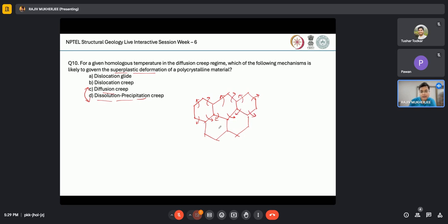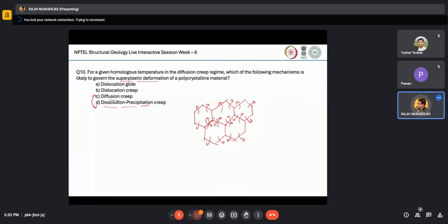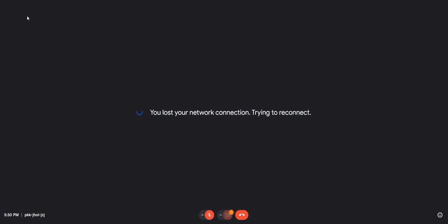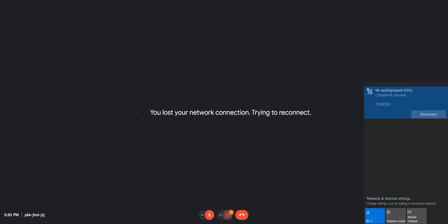Eventually, you see that in these grain boundaries, if you are present there in fluid form and you're constantly adding up with diffusion, and there is external stress, keep in mind there is external deviatoric stress, then grain boundaries become the weakest portion of all these grains,